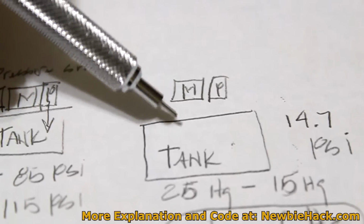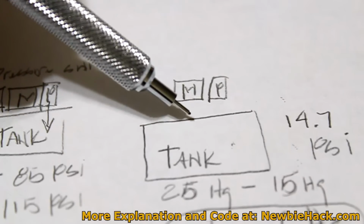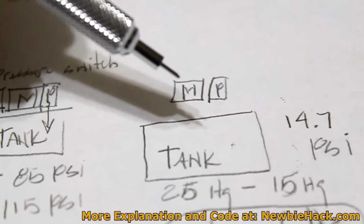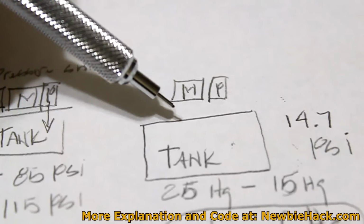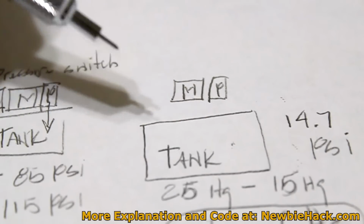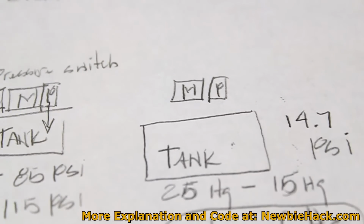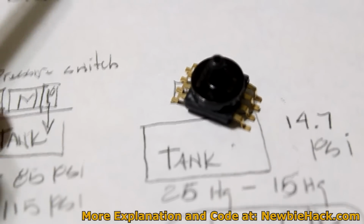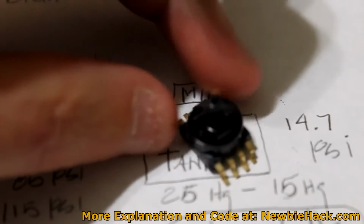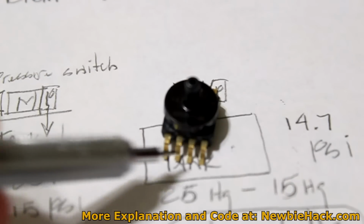You'll have a difficult time finding a pressure switch for vacuum on the internet. Generally, it ranges in the hundreds of dollars. So I'm electing to make one myself, from a discrete component of a pressure switch, which looks like this. And you'll see that there's a port on the top, and then you can use these 4 pins on this side.